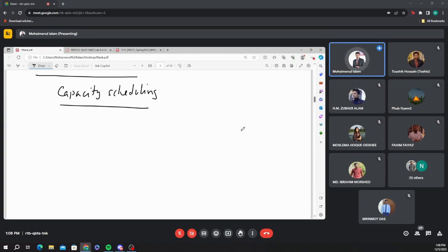So in that scenario, you need to start your generator 1, 2, 3, like that. So you cannot start the generator sequentially. You don't need to do that. Rather, you can start the generators considering their efficiency. You can make a chart of those generator efficiencies, and based on the order of efficiency, you can run the generators. Okay, turn on those generators.